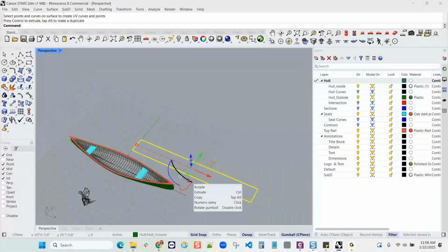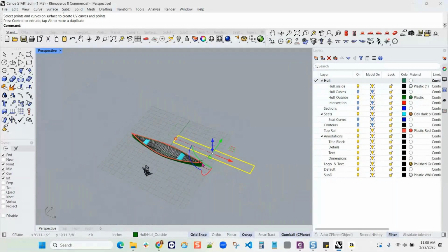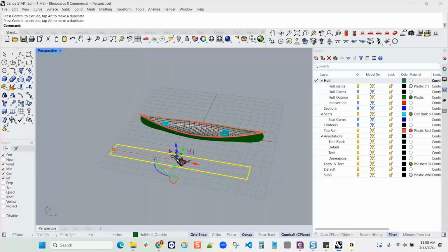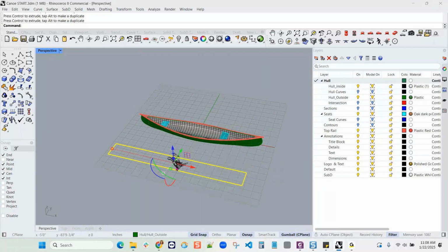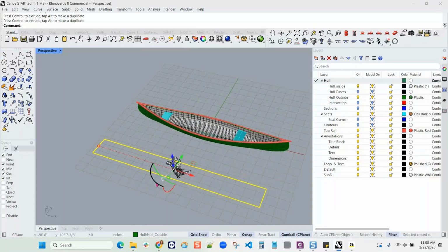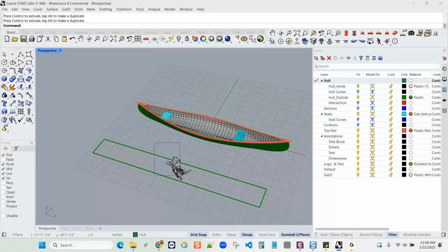space. Now, why that's important is because when we do Flow Along Surface, it's going to want a base surface that represents the surface in UV space, and then the target surface, and then of course what we want to orient on that surface or flow along that surface.